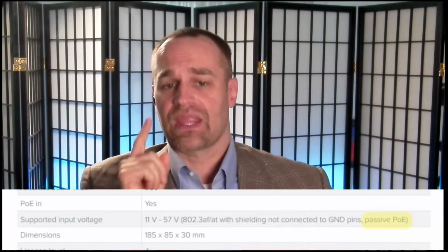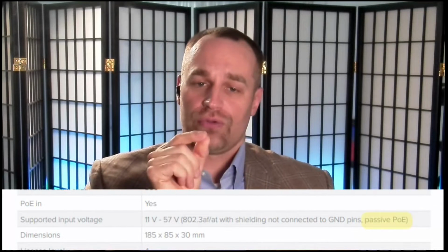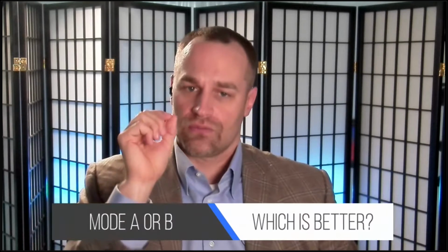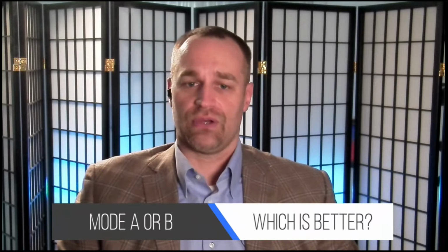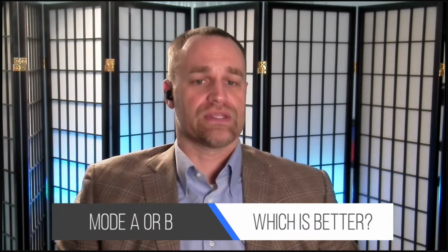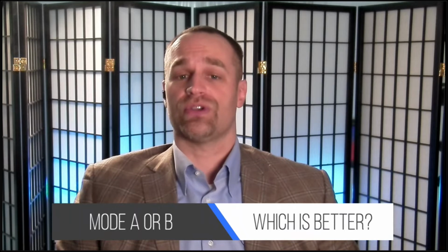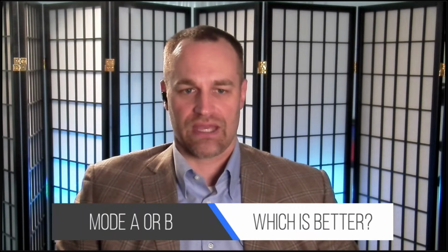There's only one company that I know that used to do an 18 volt PoE solution where they actually sent 18 volts to the network cable, but I haven't seen them do that for years. And there's a very good reason, because with PoE at 12 volts, your power loss at say 25 feet is already so high most cameras won't operate. So that's an important detail to know. There's no such thing as 12 volt PoE. Really, for all practical purposes, 24 volt PoE is the lowest voltage you'll actually get on network cable.